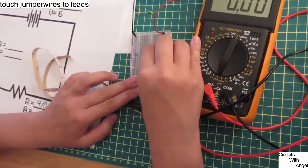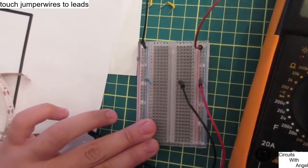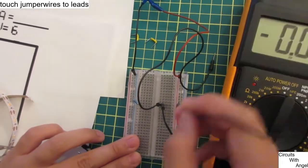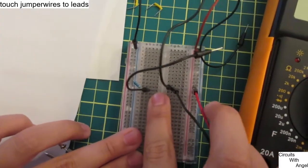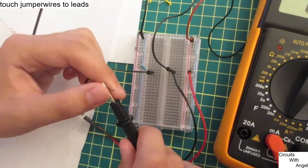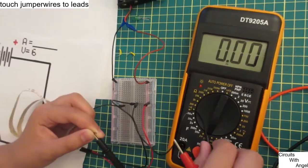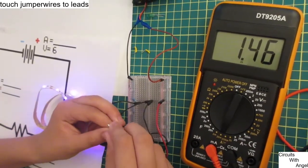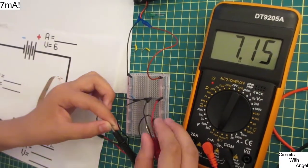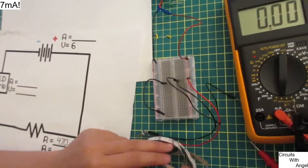And turn the settings to 20 milliamps, and after that, we move our jumper wire into an empty row in the breadboard of our LED strip and replace it with two other jumper wires that will connect to our multimeter leads. Now, we always gotta make sure that our components are in the same line as our jumper wires before we go. So make sure to check that. Alright, now we're gonna touch our leads. Alright, so I'm gonna say that's 7 milliamps, and we're gonna go write that down. That was a bit quick, but I'm pretty sure it's 7 milliamps.